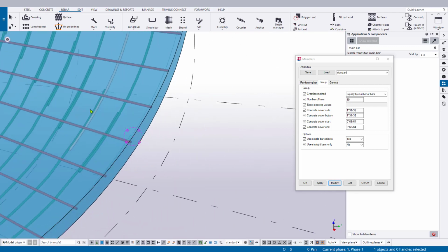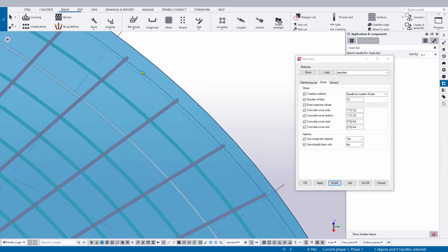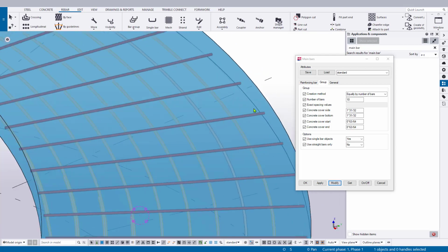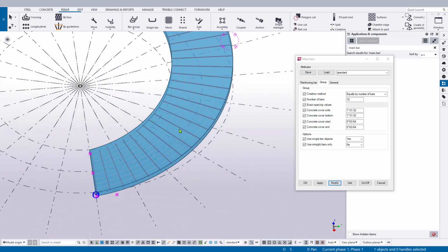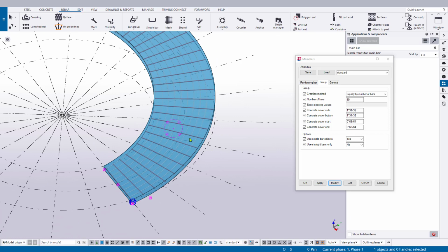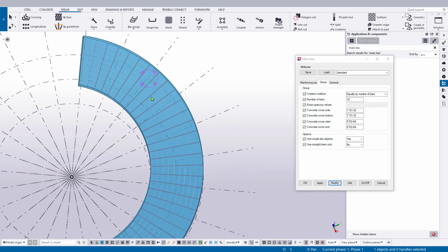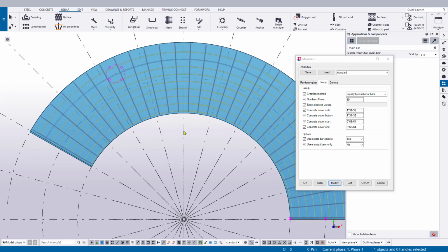You can see the splice zones being applied there for us, which is great. But you may notice at some point on the outside where you have a bar that shows up as a single line and not necessarily a solid bar, right? And this is the result of the bending radius being compounded by the tool because of its offset. And I'll show you how to fix that really quick. But by and large, what you should do is apply the tool and inspect your result. Come in and play around with the options to tweak the specifics and get as close to your configuration as you can if it doesn't give you it 100%.